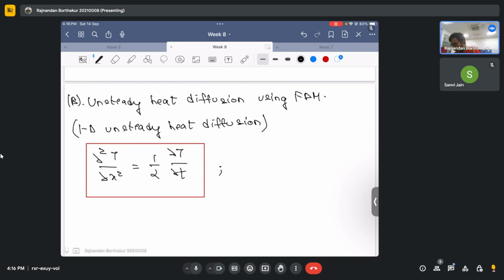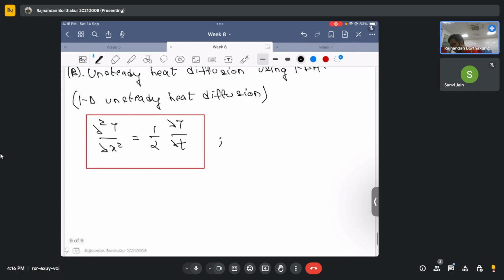So I can frame this problem as, let's say you have a rod, and I say to you that the initial temperature of this rod, I'm assuming that the width of this rod is very, very thin with respect to its length, just like the semi-infinite solution that we studied. So I'm assuming that the temperature of this rod for all x at time t equal to 0 is some Ti that we know.